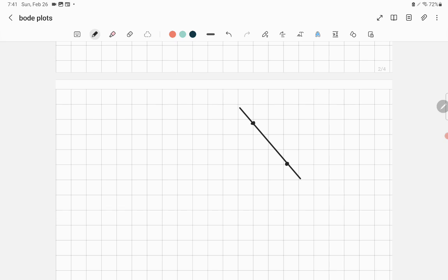How do I do that? Well, of course, you have 2 axes. This is the axis of the frequency, and this is the axis of the decibel, right? And remember, the frequency axis is divided into decades and is logarithmic. So every point has a value of the frequency. Let's call this point A. So the frequency is equal to FA, and the value is equal to A decibel. And this other point, call it point B. So the frequency is equal to FB, and the value is B decibel.